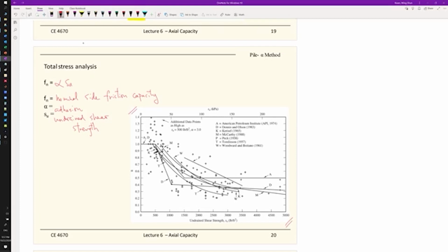to find directly, related to the side frictions for clay piles, different piles. There are quite a few different existing methods, and they are more or less similar in relating the alpha and the undrained shear strength of soil. Some popular ones are Tomlinson 1957, a classic method. And again you see API, the American Petroleum Institute. It also gives you some recommendations.